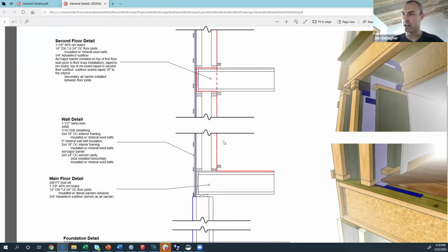Because then you would have vertical studs when it comes to installing cabinets, when it comes to installing a microwave or a television, mounting that on the wall. When it comes to installing drywall and stuff, just the vertical wall framing is something that is really easy and people are used to. I also probably, if I had to do it again, I wouldn't build a 2x4 exterior structural wall. I'd build a 2x6 wall just because, from a bearing perspective, it gives you more room for weight. We've got a lot of snow up here. It's just a little bit stronger.